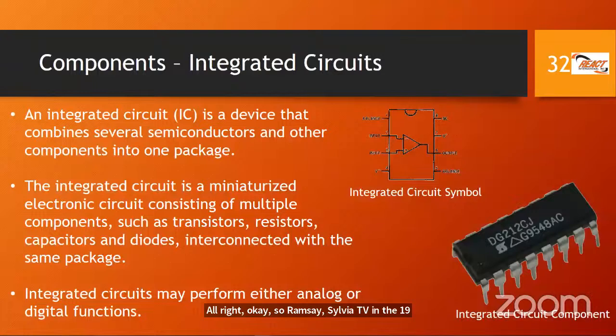Right. So now, Fahad, no battery should be discharged completely, right? Each of them will have a minimum voltage threshold beyond which you can damage them, right? So each one will have a difference. Some of them are deep cycle and they can go low for a little bit longer and at a slightly lower voltage, but no, you don't ever want to completely discharge. So yeah, good question.